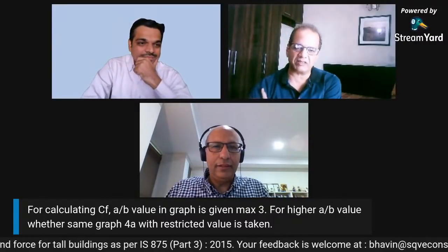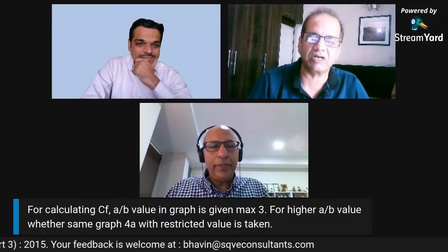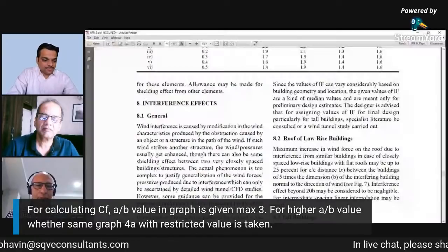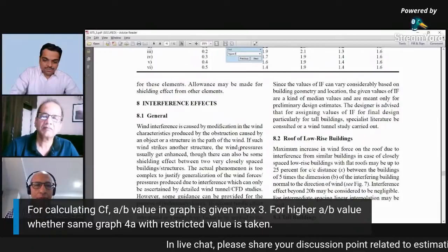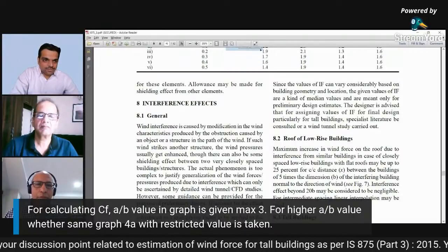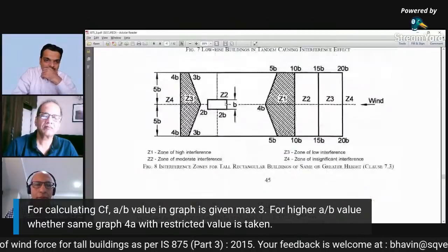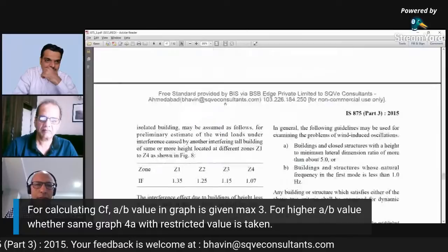And other codes, I think the Australian code, Tony, you have formulas. The Australian code doesn't go past the 1 to 3 aspect as well. And in fact, the new code that's about to come out in Australia will be excluding buildings with a longer plan aspect ratio from being covered by the code. So there's a limit.